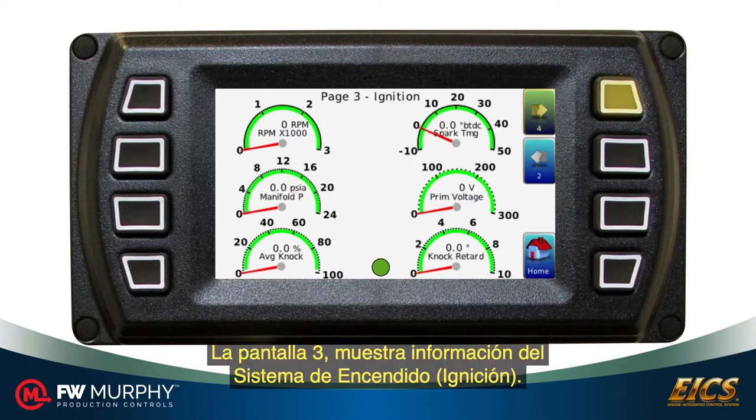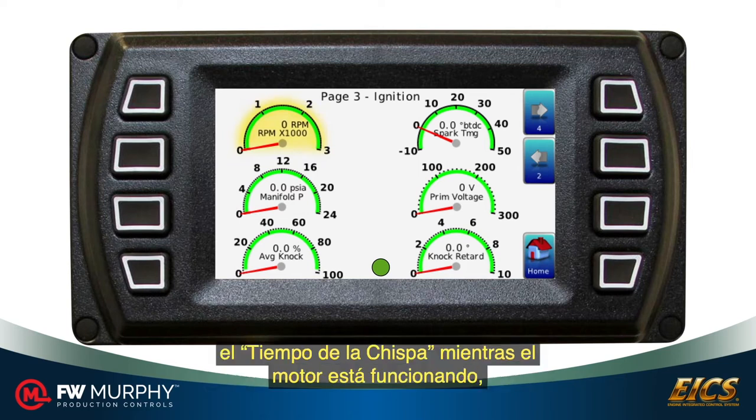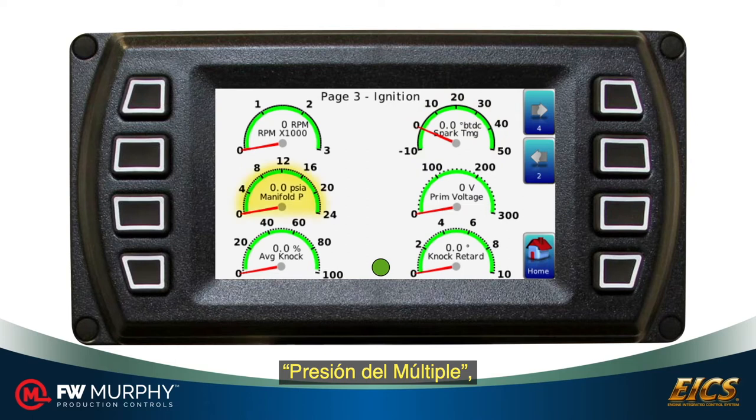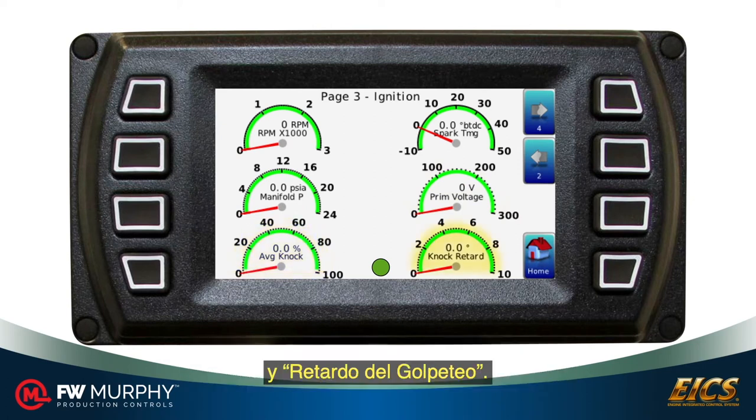Screen 3 shows ignition information. Again, we show RPMs. Also shown is ignition timing as the engine is operating, manifold pressure, primary coil voltage, engine knock, if the engine is set up with detonation detection or knock detection, and the knock retard.